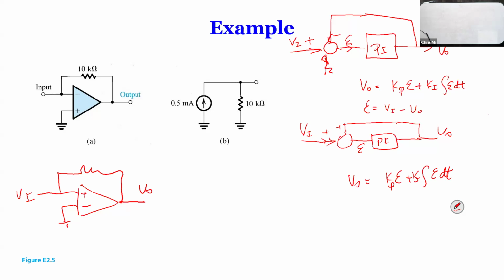What you're doing is taking VO and VI and adding them. If you add them, your epsilon becomes bigger, so this becomes bigger, right? Every time your VO becomes bigger, this is even bigger, and then eventually you saturate. If VO is negative and VI is positive, eventually you'll go in the other direction. So positive feedback doesn't really work.